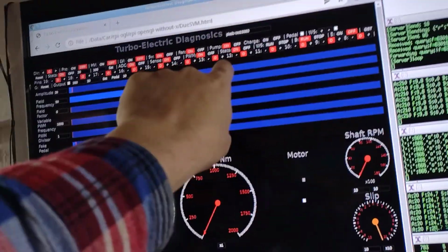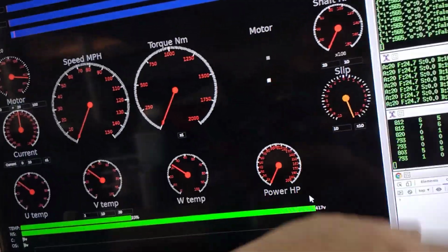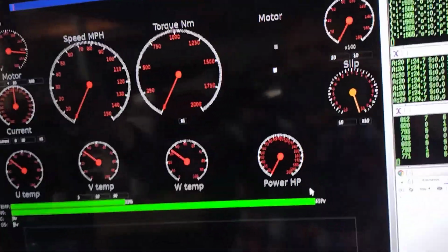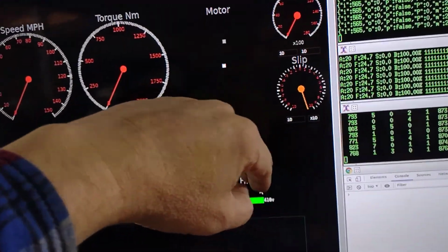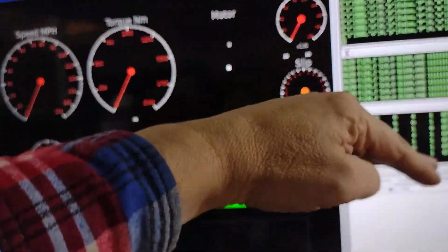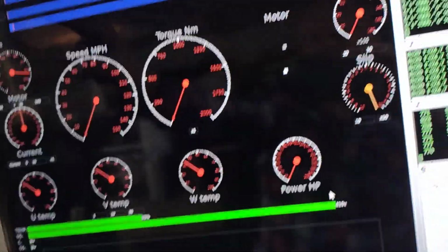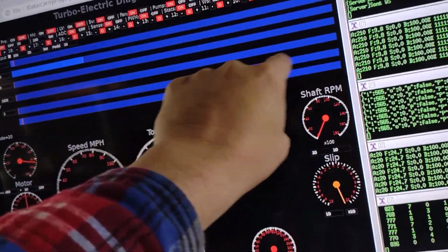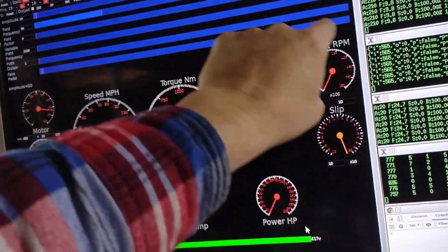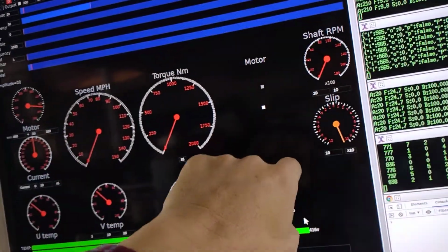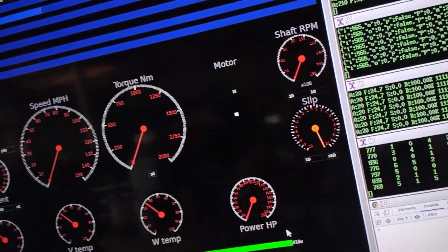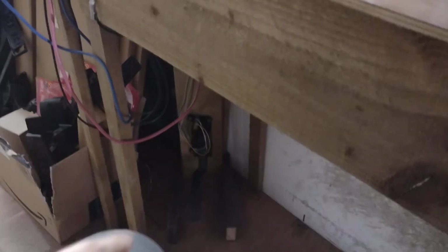So as you increase the amplitude, then obviously the slip will come in as the motor speeds up on its own because it's a base frequency, right? So as you bring the pedal in, it speeds up the motor to lower the slip, and as the slip lowers, the frequency of the stator increases so as to keep the slip within certain bounds, which means basically the motor speeds up.